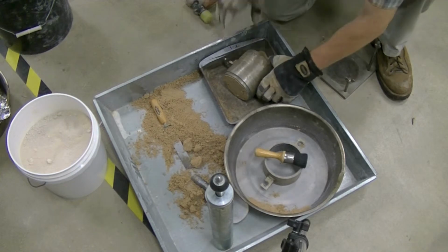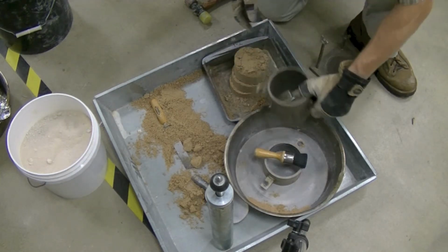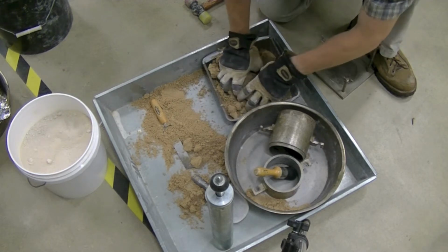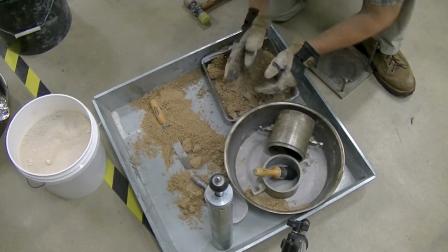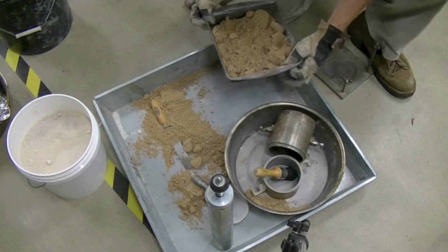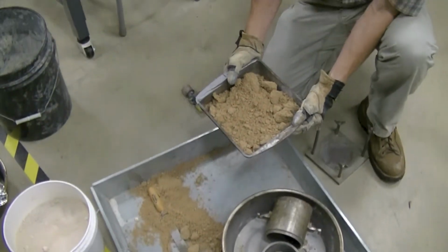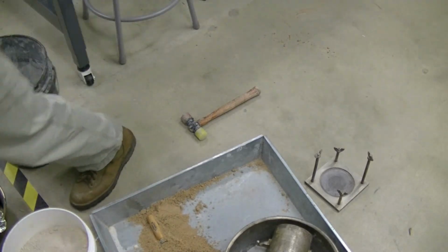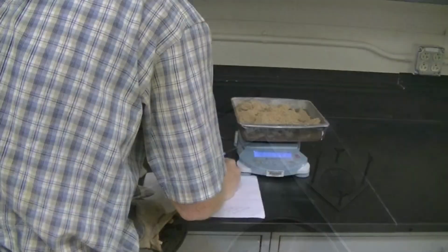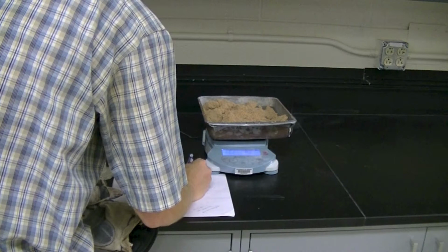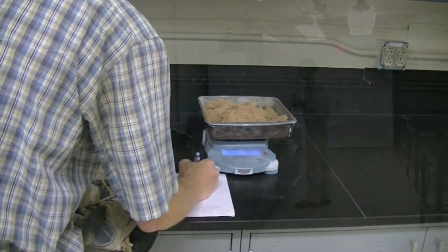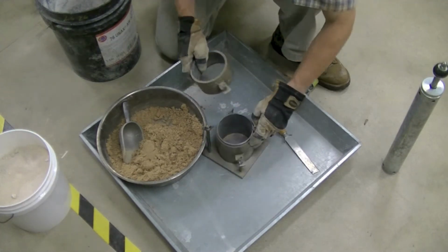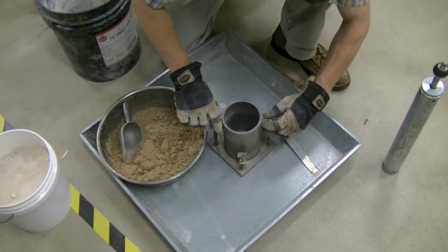Use a hydraulic jack or hammer to extract the soil within the mold. The most consistent moisture contents come from weighing the whole pill. Once the soil is extracted, break it apart so that the material can fully dry. Transfer the soil into the tare. Weigh the material and tare and record this value. Place the moisture content sample in the oven to dry at 110 degrees Celsius. Repeat this procedure for the remaining subspecimens.